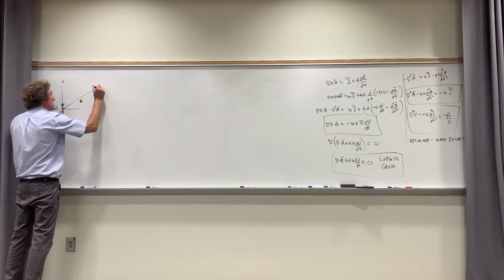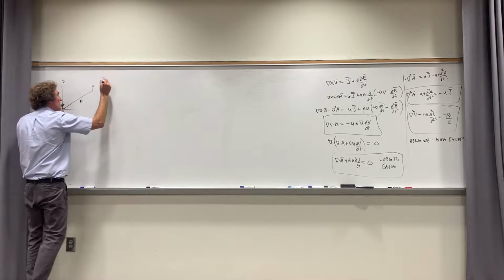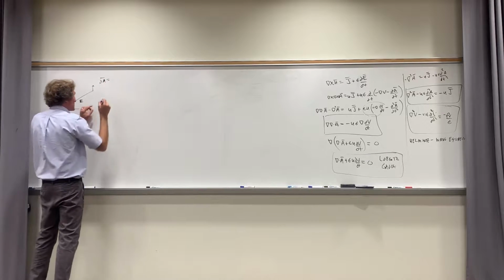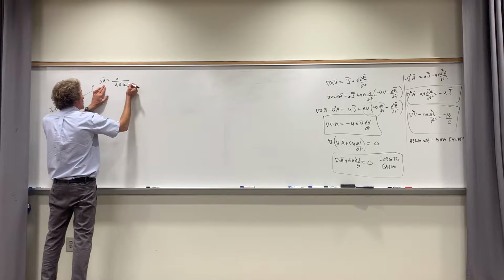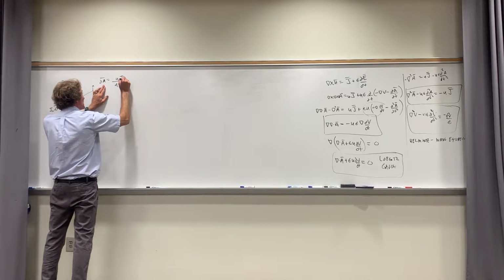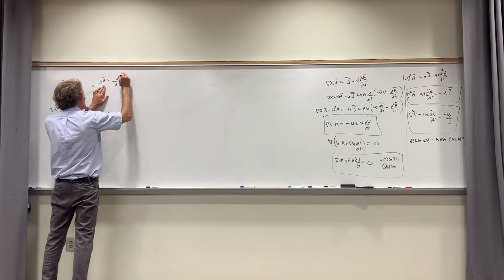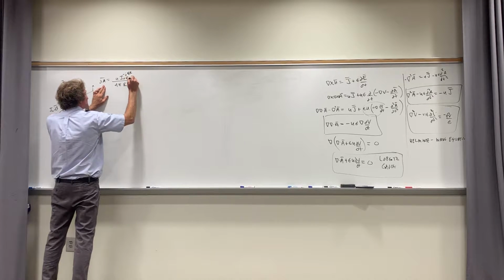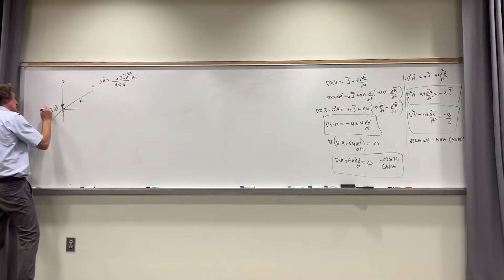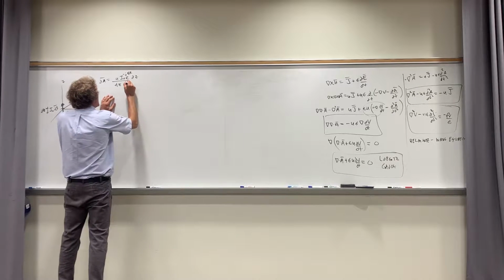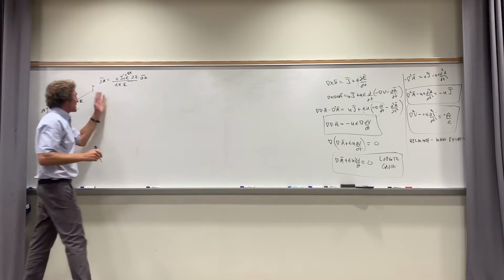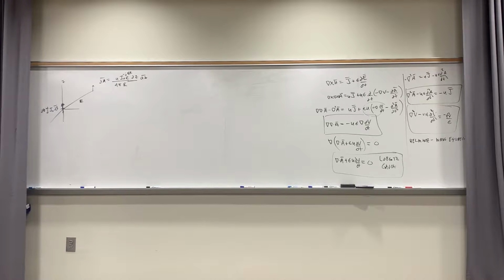Now I can say that my differential A vector, the differential magnetic vector potential, is equal to simply mu over 4 pi divided by r, times I naught e to the minus j beta r, and it's going to have the dz in it because I have dl, the differential length has to be in there. And it's in the az direction. That's it. That's a differential form of A.